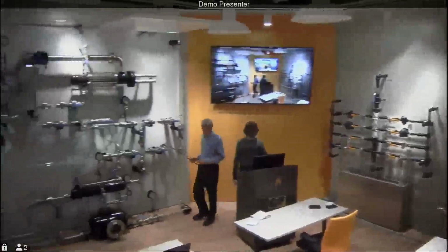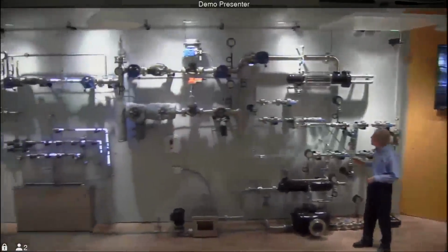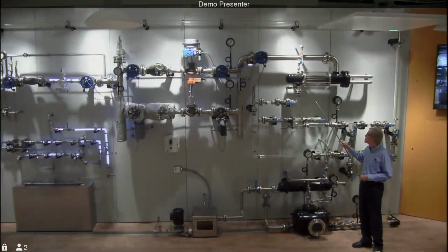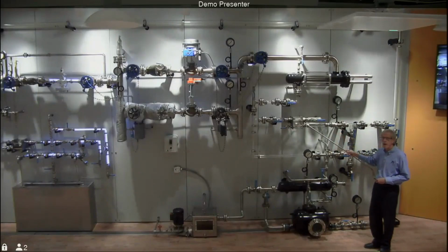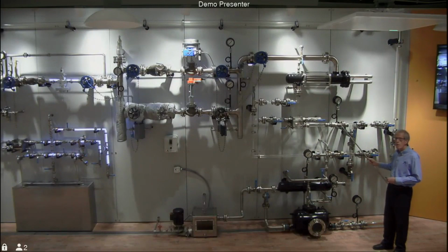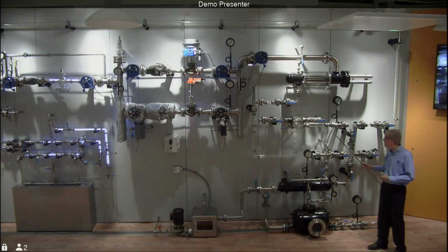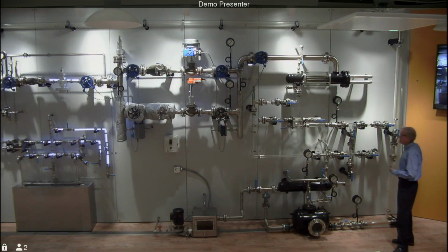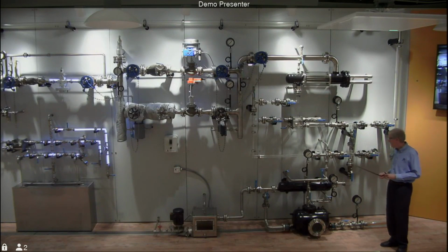And then finally, we have a glass low pressure trapping demonstration here, a glass heat exchanger with glass piping, glass bodied steam trap, and then piping where we can demonstrate either drainage with the benefit of gravity from the steam trap or going overhead, attempting to lift the condensate with a modulating control valve.